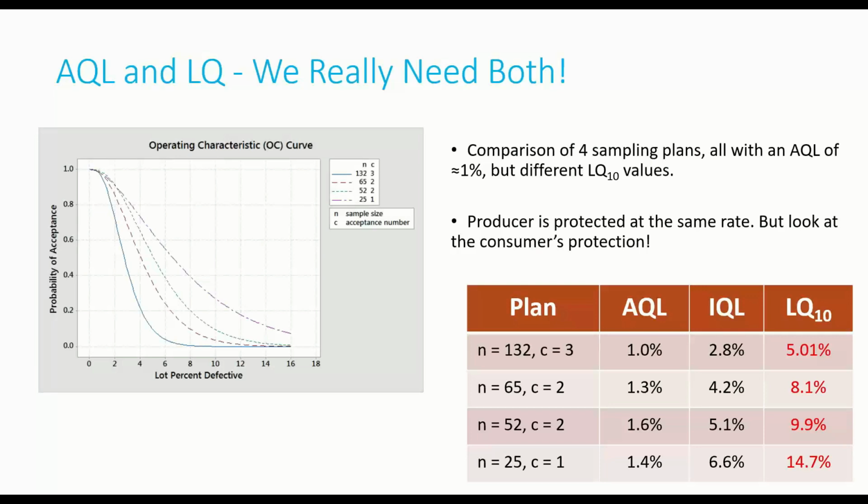The only time you'll be looking at the whole lot is when you reject. So there might be times when, even though we're randomly sampling, and as long as you pull that random sample it's supposed to help control for this, maybe you still do get lucky. We're only allowing like a 95%. That means 5% of the time you could just get lucky and pull a really good sample out of that lot, and there are defectives hidden in there.